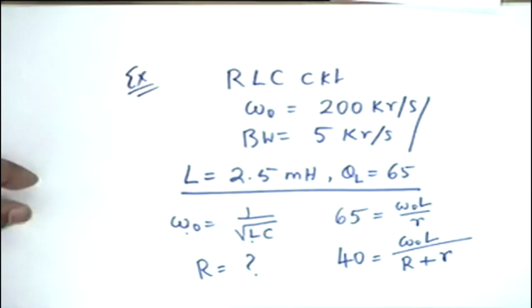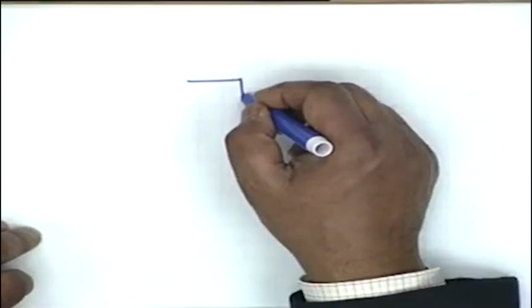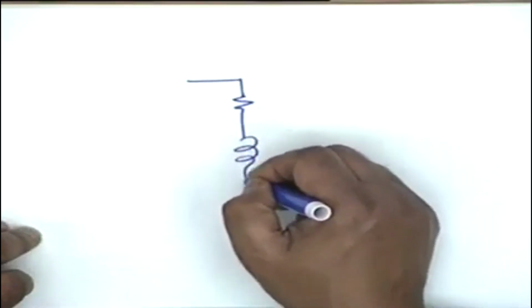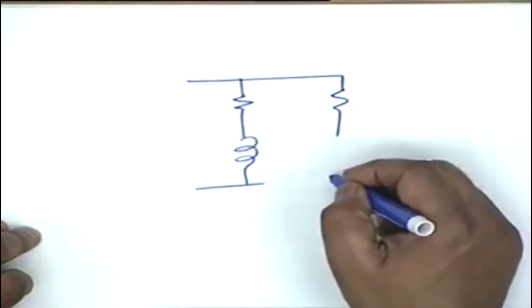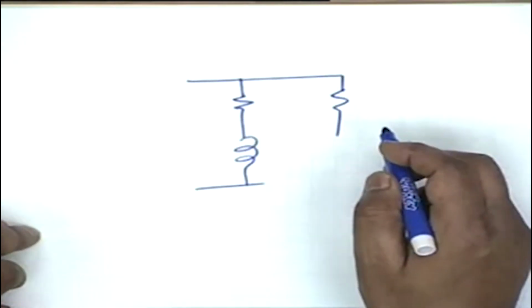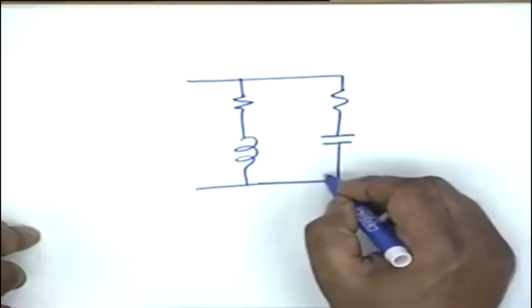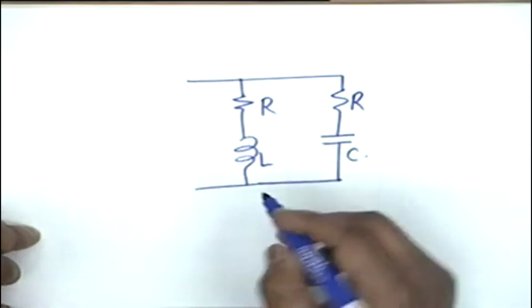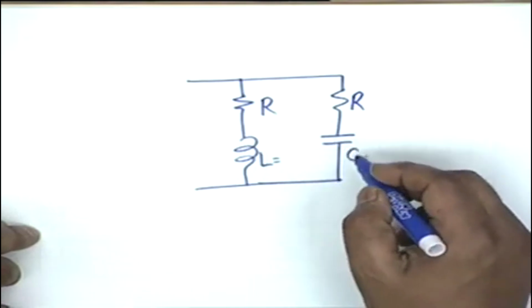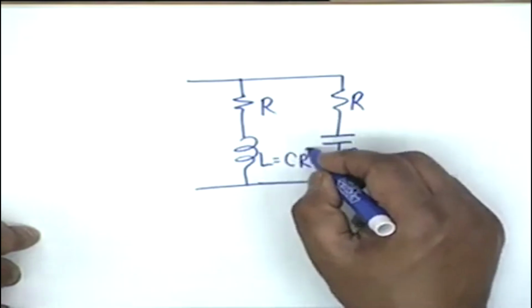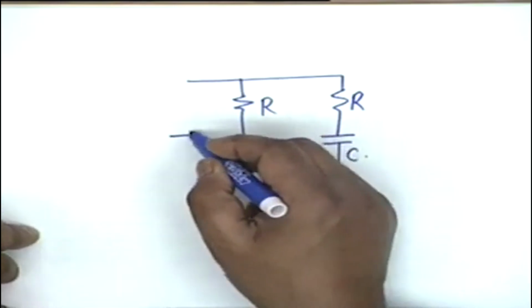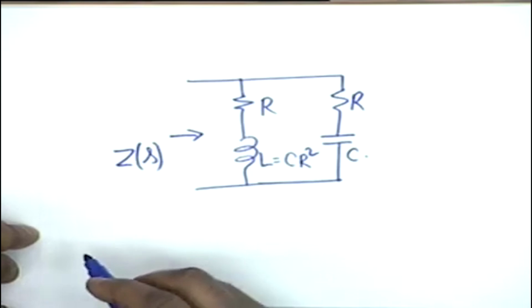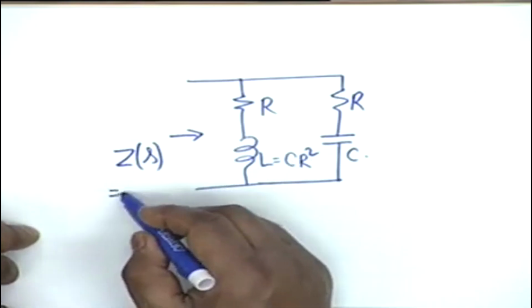Okay, one problem, and the other is a problem to be left with you. It's the problem that we had talked about in one of the classes when the lights went off. It is a complicated resonance circuit. It is a parallel resonance circuit in which L and C are in parallel, but unfortunately both of them have a series resistance of capital R, and in addition the elements have so conspired that L is equal to CR squared. You can see that the impedance, if you calculate in terms of S, is simply R.